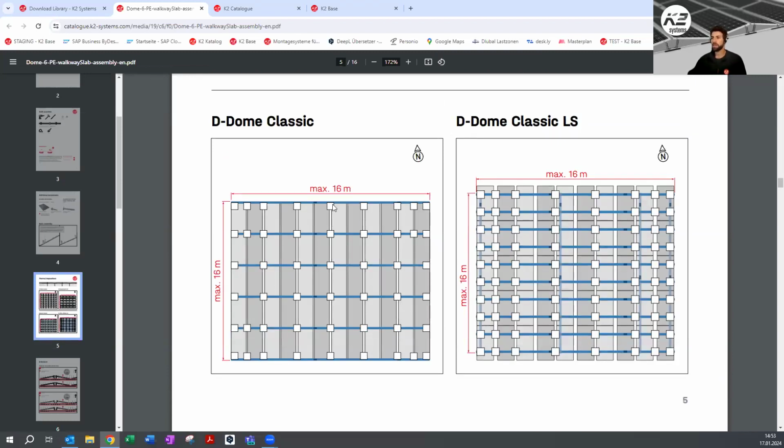But sometimes there are squares that are red and there's still a number inside. If there's a number inside, that means there is still one concrete block or PE plate and you need additional ballast, which can be worked out with either extra concrete blocks on top, or extra PE plates or blocks underneath the rail. So you're always on the same level under the rail in general.